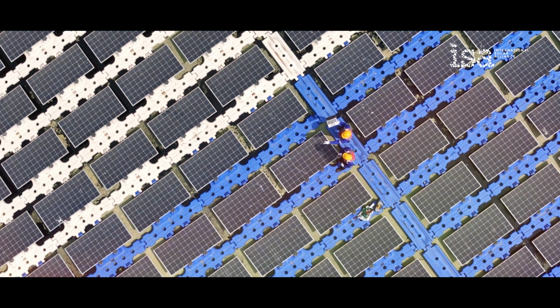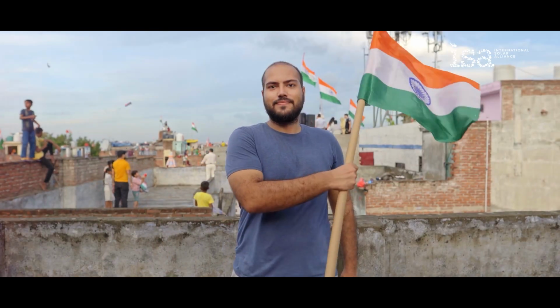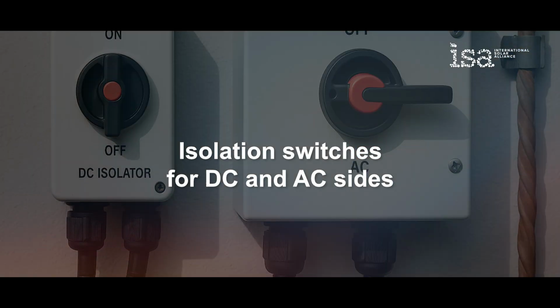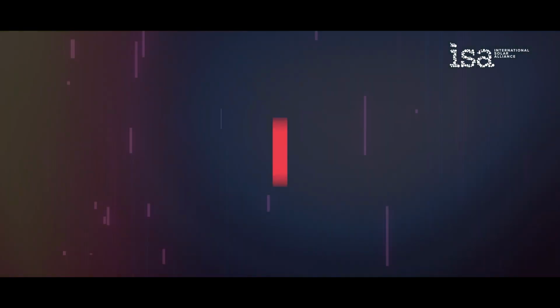Safety is paramount during installation, operation, and maintenance of grid-connected DRE systems. Compliance with local regulations ensures personnel safety and grid reliability. Proper earthing and lightning protection systems. Isolation switches for DC and AC sides. Certified metering and anti-islanding mechanisms. Adherence to local grid codes and safety standards.